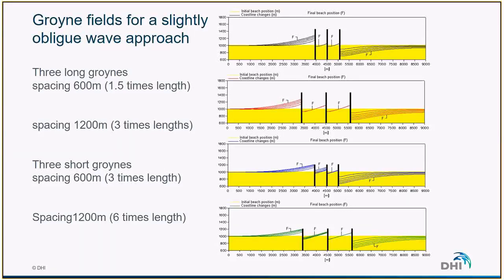To conclude on the groins, the groins are less and less used today because they have significant drawbacks, especially the downstream erosion, and also the dangerous currents created by the structure. On top of that, it obstructs the passage to the beach because it has to block the entire beach. And it's not a very beautiful element. However, if a project includes groins, even nowadays, usually some filling will be applied in order to avoid the temporary erosion and therefore reduce the side effects of the construction.